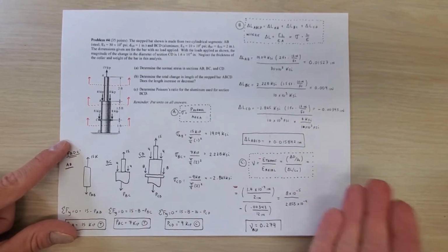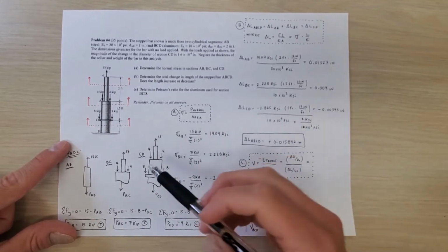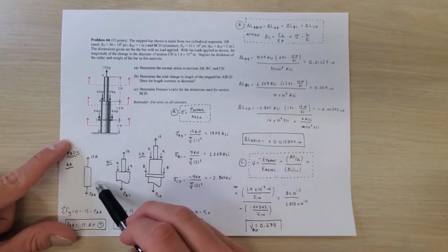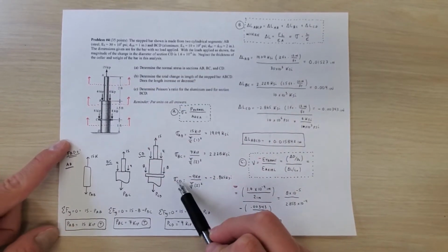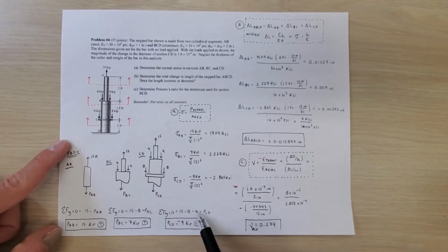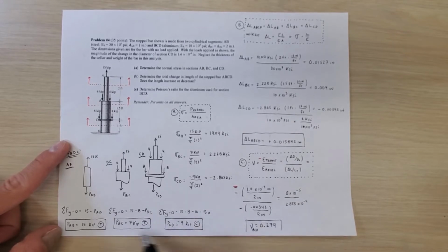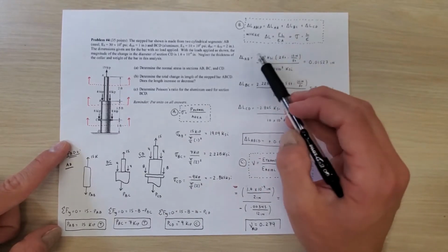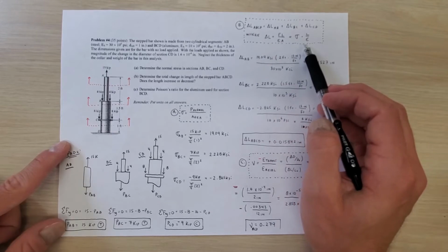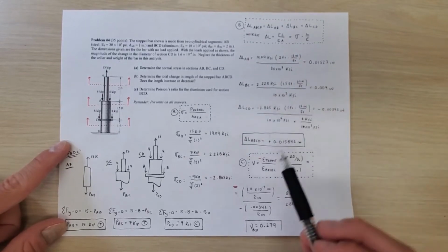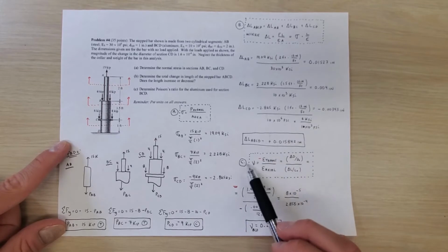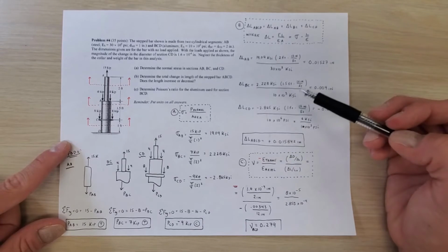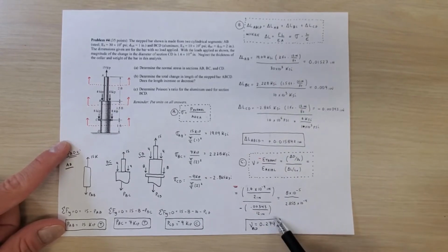And that is how you approach this stepped rod problem, which essentially asks you to take the section cuts, which we do up here. We draw the free body diagram for each section cut. We do a sum of the forces to find the normal force in each section. And then once we knew those forces, we were able to find the stress. Using the stress from part A, we're able to solve for the change in length in each segment, which we did right here. And in the last section, we just had to solve for Poisson's ratio. So we used our equation right here, plugged and chugged all the numbers that we had been given and solved for in the previous steps. And we get our final answer right there. So there you go.